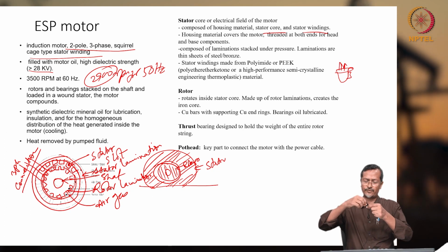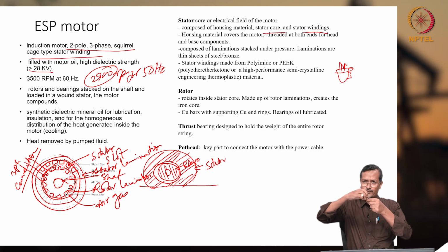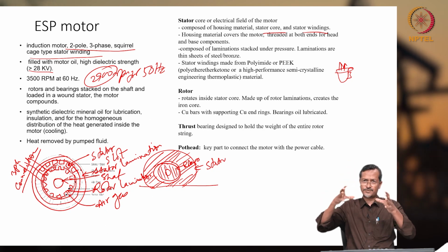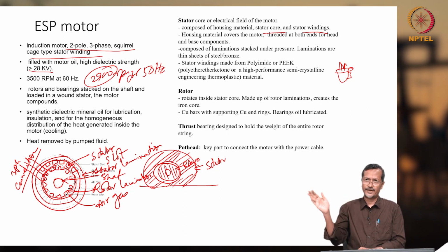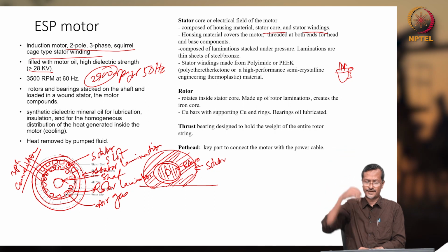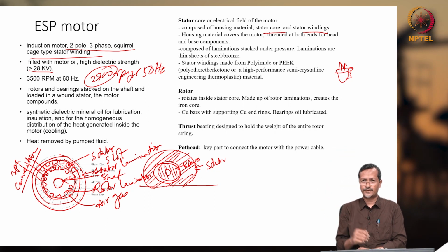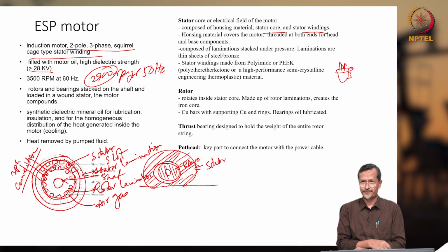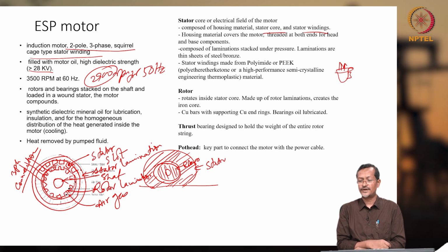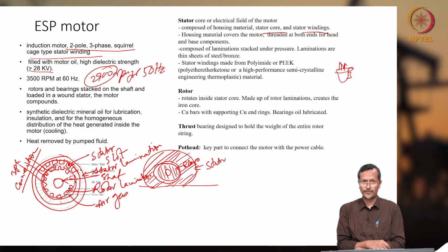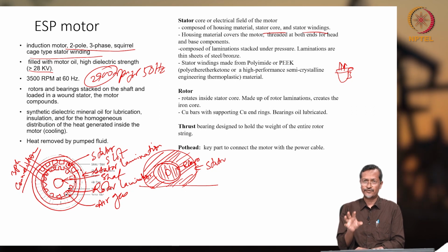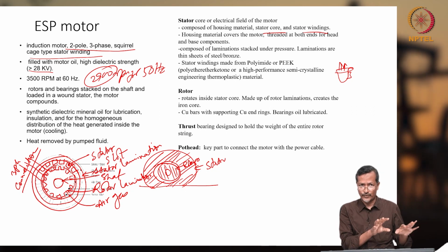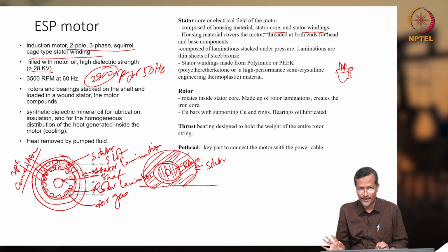Because of natural convection, liquid particles move to the liquid surface, and slowly it cools down. It takes some time, but if you have an air blow or an overhead fan, lots of forced convection heat transfer will happen, so your cooling rate will be higher. That is why this fan is there. Because of forced convection, motor temperature goes down, so normally there is a motor fan.